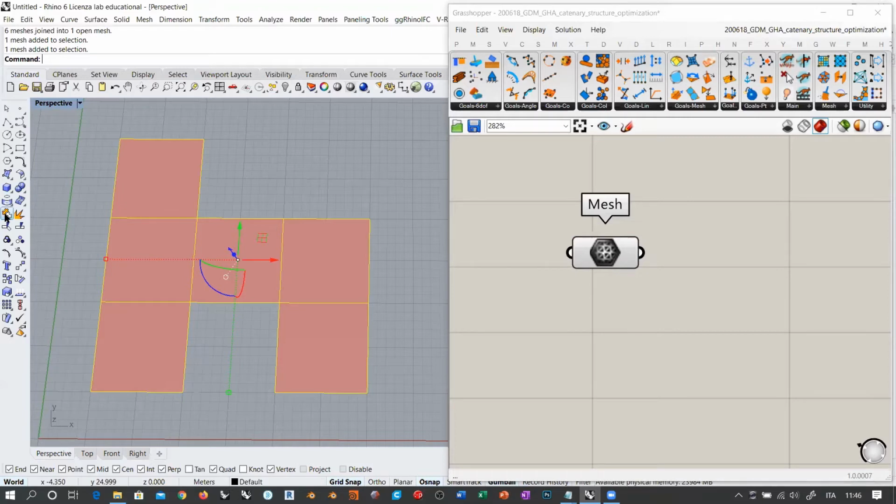So it's not a dedicated mesh command. Now, joining meshes is not like joining surfaces or joining lines, okay? Many bad things can happen. So if I do this and I say, okay, I have one mesh with 24 vertices and 6 faces right now, I do expect this mesh to work like one single mesh with these features,